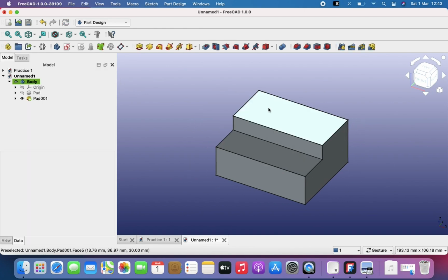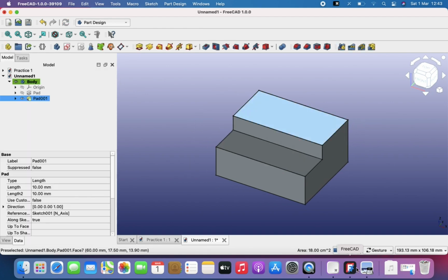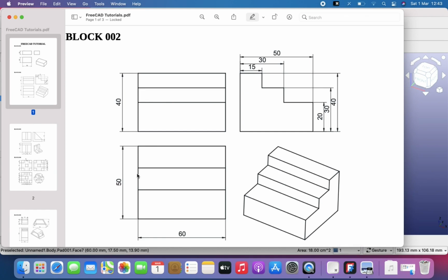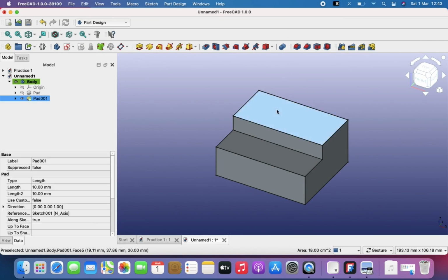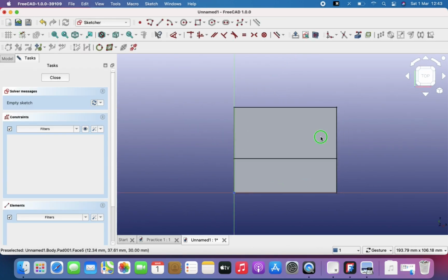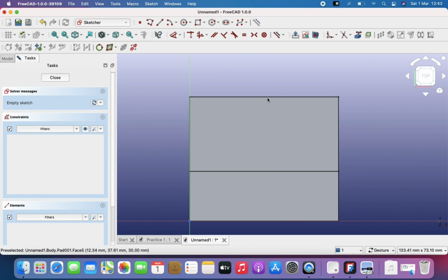And finally I'm going to create another sketch on this plane as well, and that will be this. So if we look at this top here, that's 15 by, this is 40 minus 30, which is also 10, so 15 by an extrusion of 10. So I'm going to create a sketch here, go to create sketch, and then firstly I'm going to project the lines so that I can use them in my new sketch, and there, and there. So now I have those lines projected.